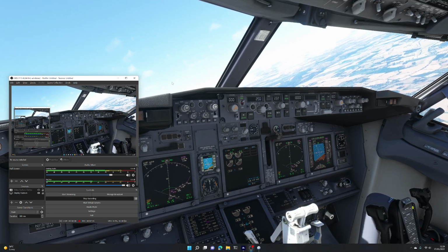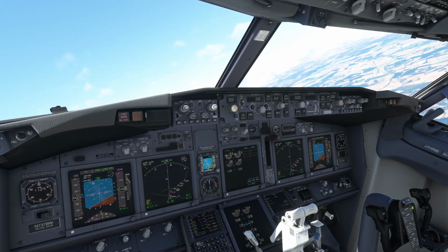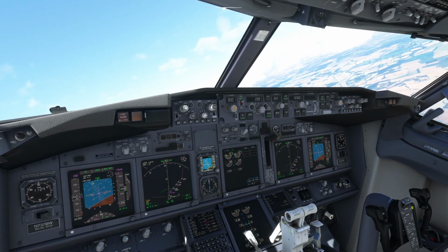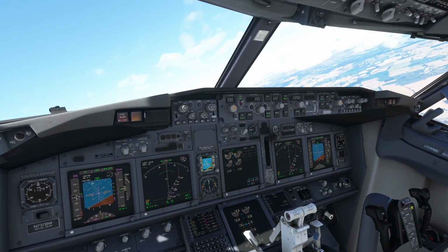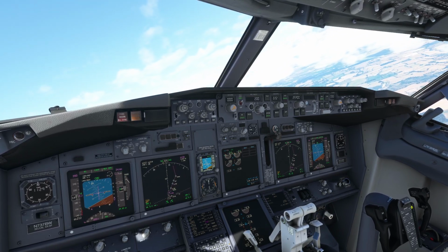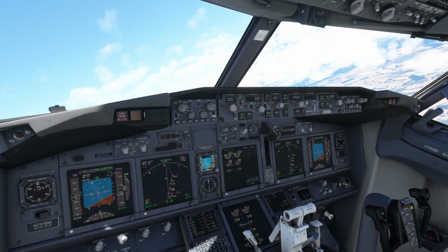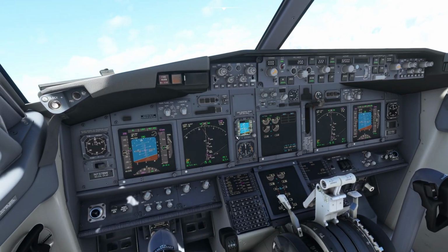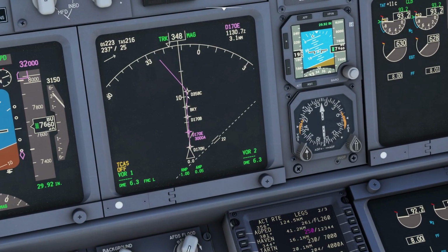Okay, so you rejoin me and we're climbing out of Stansted. We're on a level change up to 10,000 feet at the moment, so we'll continue that up to 32,000. It really makes no difference to us at the moment. So we're not going to get into using the master control panel today, but we are going to have another look in a moment at the flight management computer. And the first thing we're going to do, just get this rolled round to 32,000, there it goes. Okay, so you can see there are the waypoints of our standard instrument departure from Stansted ahead of us.